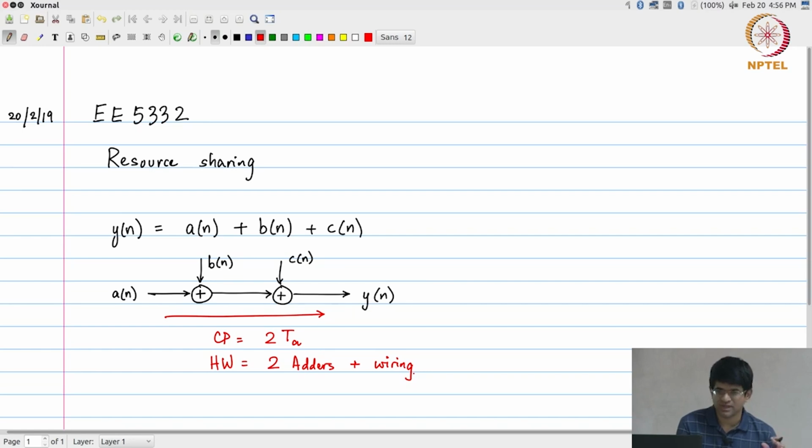But I am going to ignore that for now and assume that if I have two hardware adder units, they dominate my area. A lot of this analysis makes assumptions of that sort. In other words, it assumes that my primary goal is to reduce the number of such hardware units. Later on we can see, if I actually want to reduce wiring, if I want to reduce the number of multiplexers and all, how do I handle it?